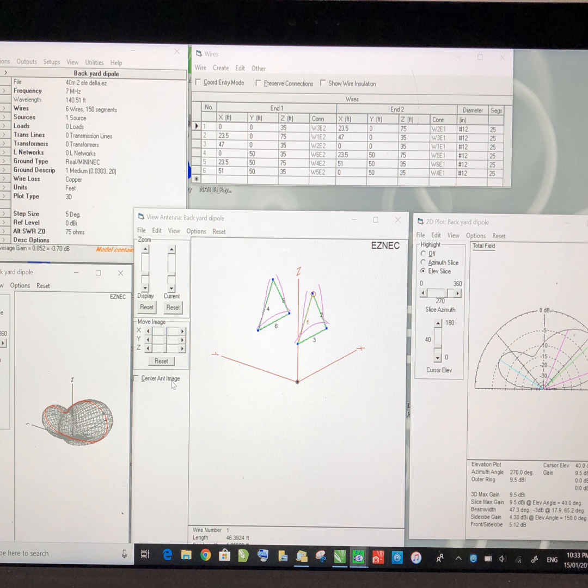But you can do all this out in the field with an antenna analyzer, a length of coax connected to the center of the antenna, and it's again a great time saver. And I've found that once I get the result right with this, I plug it into the radio, everything's normally very good. I can't think of a single instance where the antenna analyzer hasn't given me the match that I would like on the radio. Sometimes you can get various lengths of coax that don't necessarily work with certain frequencies, but I would first of all concentrate on trying to get a good match with whatever length you have there.